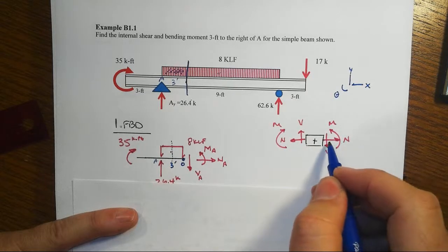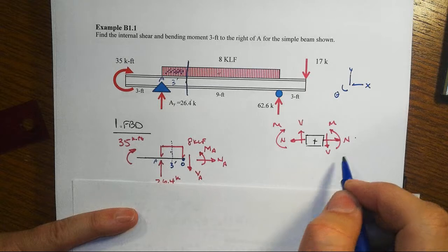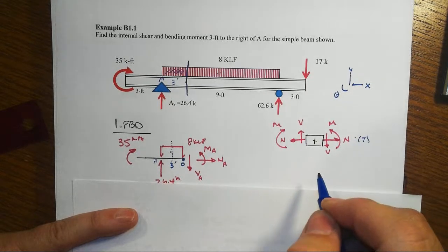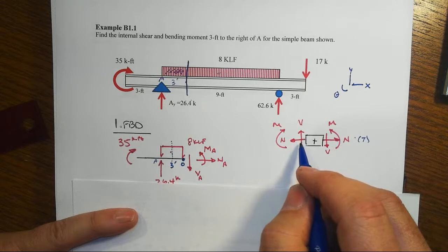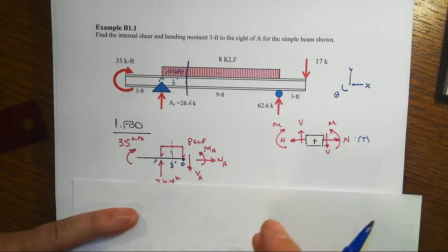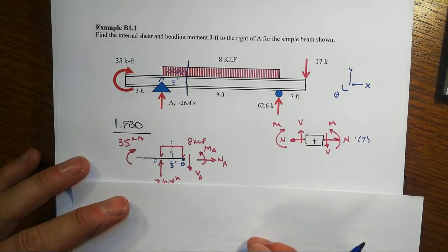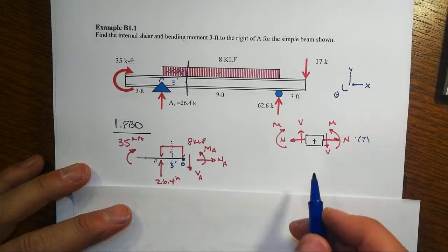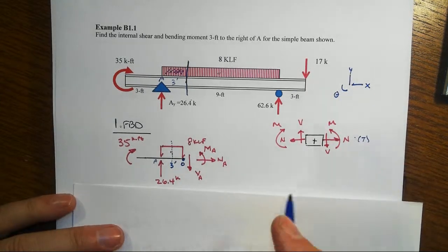Usually people like to use the axial forces as being tension, and that's positive, they say. And then the shear, I have a hard time remembering. It's up on the left, downwards on the right. I have other devices that we'll learn about in later modules to reverse engineer what that positive direction is, but I sometimes have to think very carefully about what that is and go back to a drawing like this.